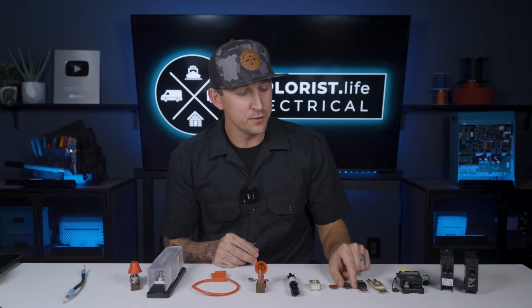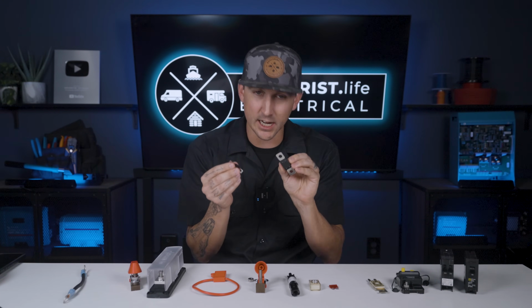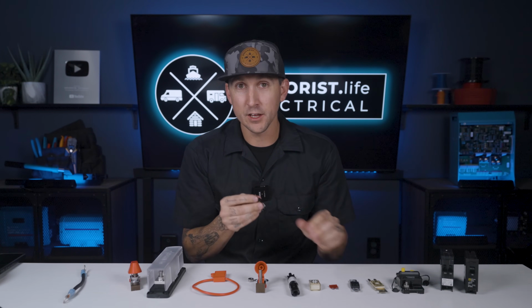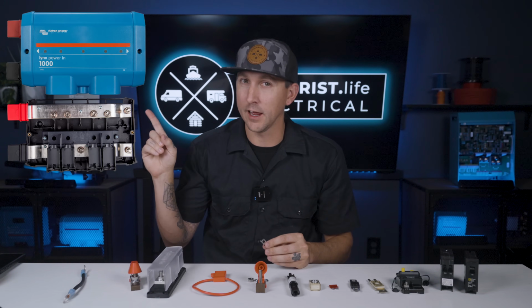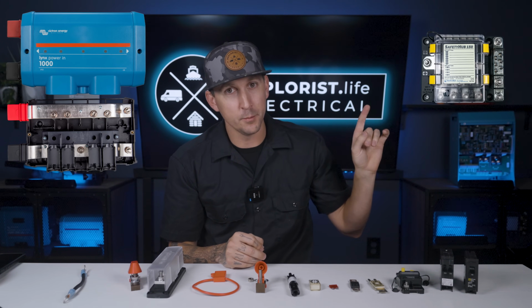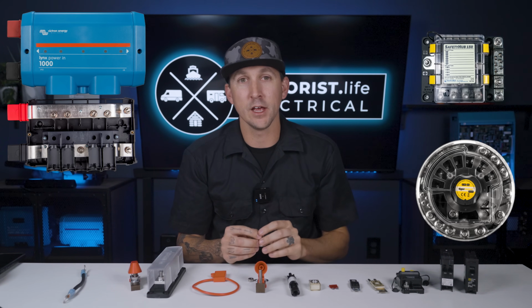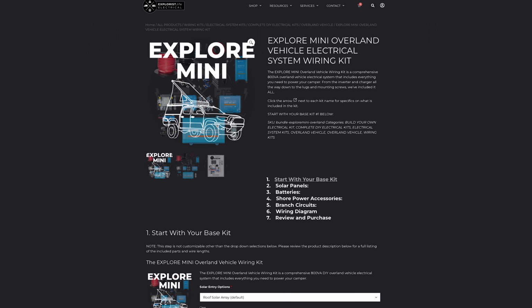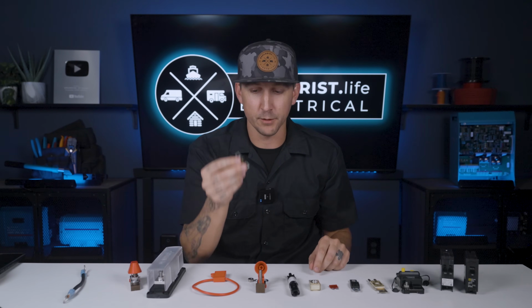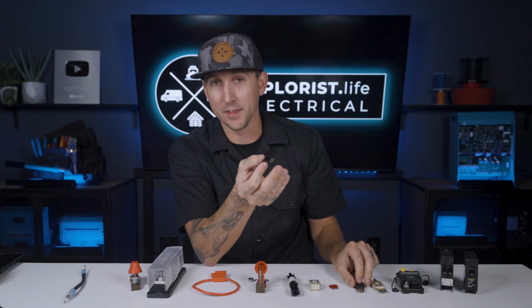We also use the MIDI fuse in place of the mega fuse, depending on the system design that we've got going on. So if we're not using the Victron Lynx distributor, and instead you're using the Blue Sea Safety Hub or the Tiger Expedition UFO 200 like we have in our Explorer Mini system, the fuse holders of those two devices just accept the MIDI fuses over the mega fuses. Since that's what that particular device calls for, that's what we're going to use.